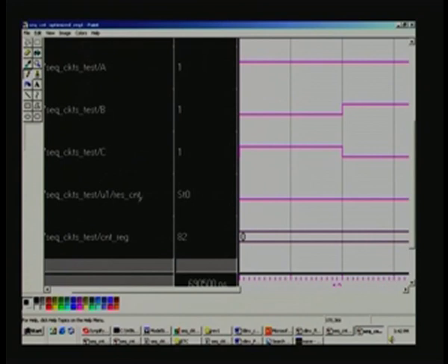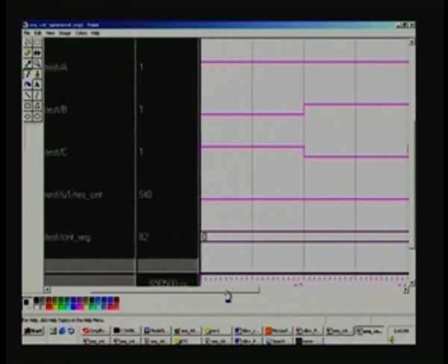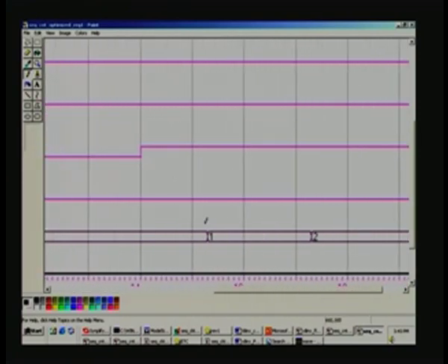So we have a reset counter as before, but there is no advance counter. I think in optimization it might have removed that signal, because the same signal might be appearing elsewhere with some other name, because we had a conglomeration of different circuits. So that may be the reason. I couldn't find that signal, advance count. That's why I was saying, while optimizing, a duplicate will not be created. It will be mapped just one time and then reused at different points. And here you can see again the counting advancing.